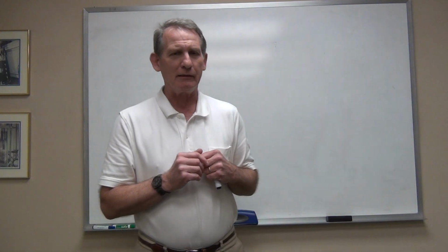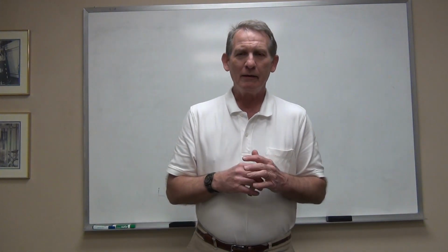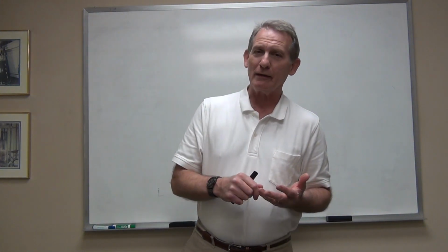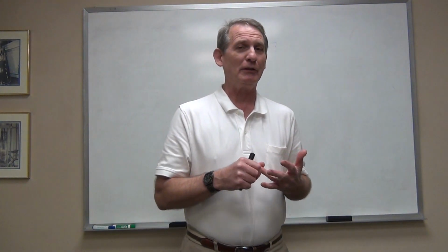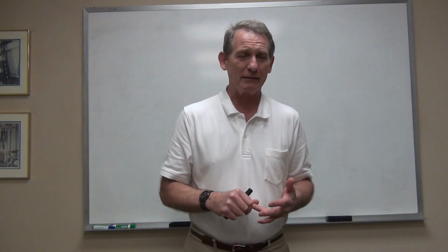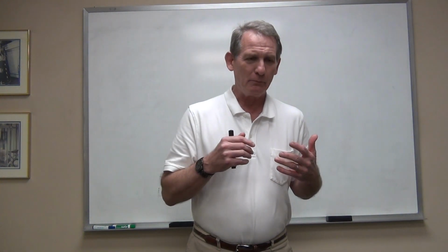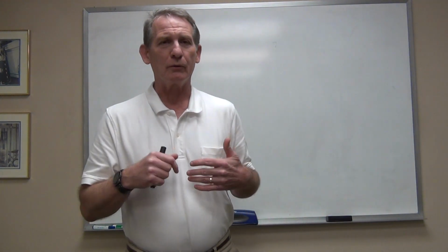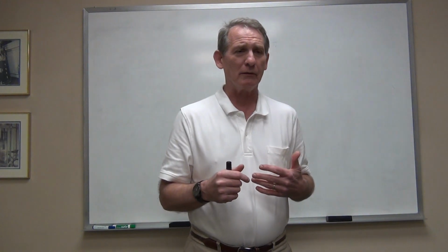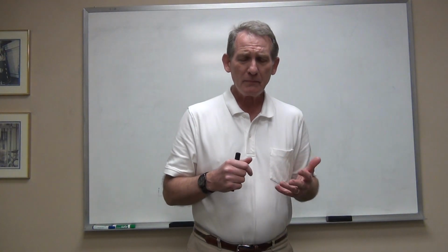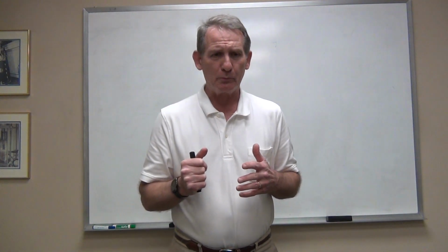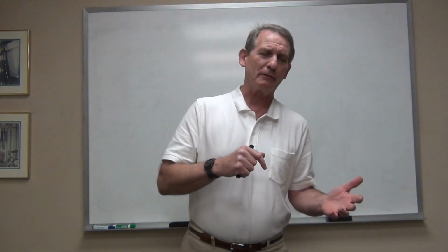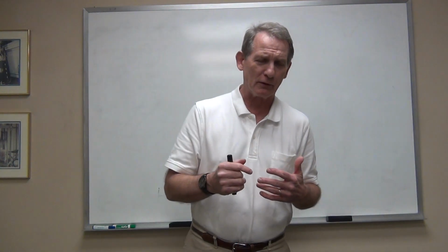I just want you to be aware that every representation of GD&T you see on a drawing, one, it's not always right. In fact, in my experience, 75% of the GD&T that I see on drawings is poorly thought through or just doesn't make any sense at all. It's an unfortunate fact, but a lot of people who do put the information on the drawing really don't understand the system very well.